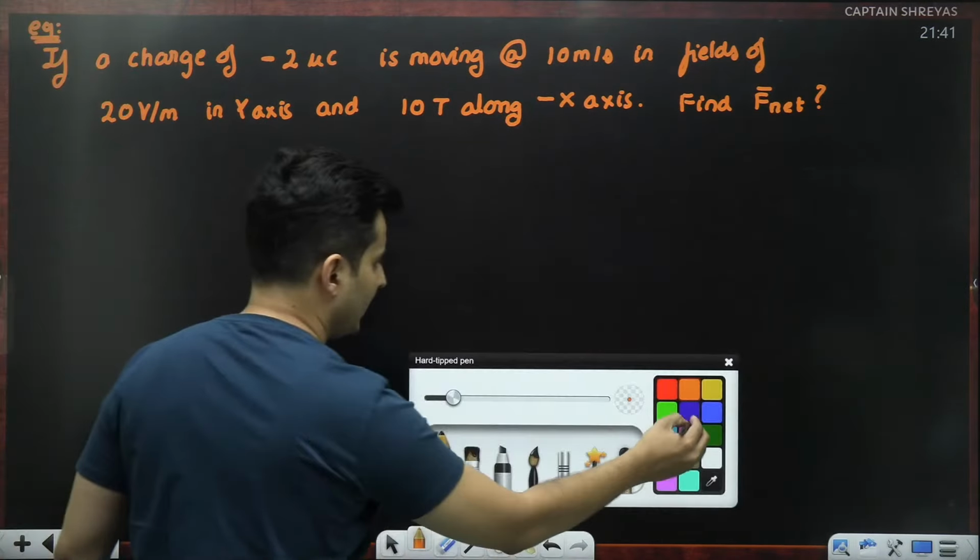Why don't we use v sine theta? Because pitch means you're going along the axis, so you have to use v cos theta. That speed into the time. I'm going with a constant speed, so in one time period, how much did I move ahead? This distance depends on the axial speed, which is v cos theta, not v sine theta. Is that okay?